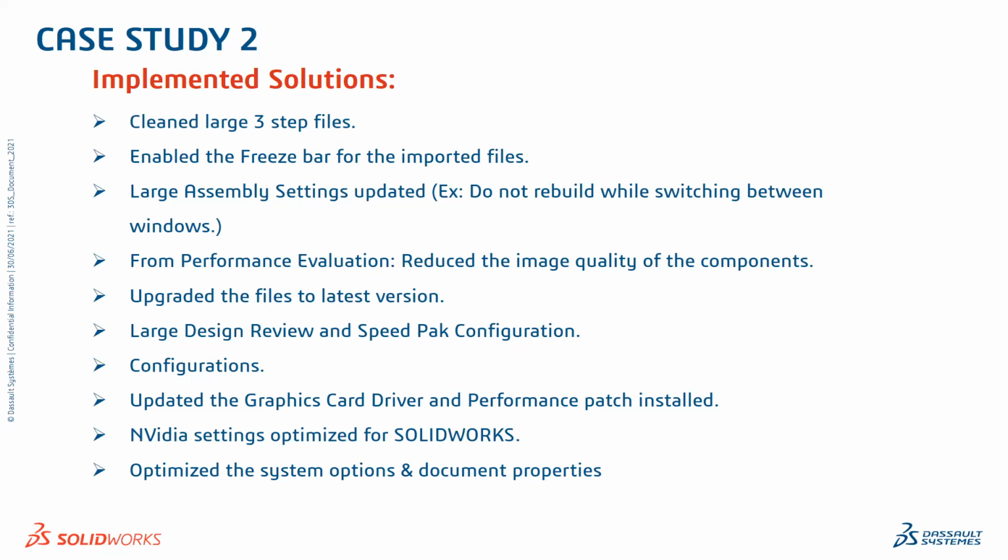If you go through these things, you will understand that whatever we have discussed, everything is being used here. So, use of Large Design Review and the SpeedPak configurations, and the use of configurations effectively. And also the graphics card was updated. NVIDIA settings were optimized for the customer's requirement. All the system options and document properties have been updated. So these are the implemented solutions.